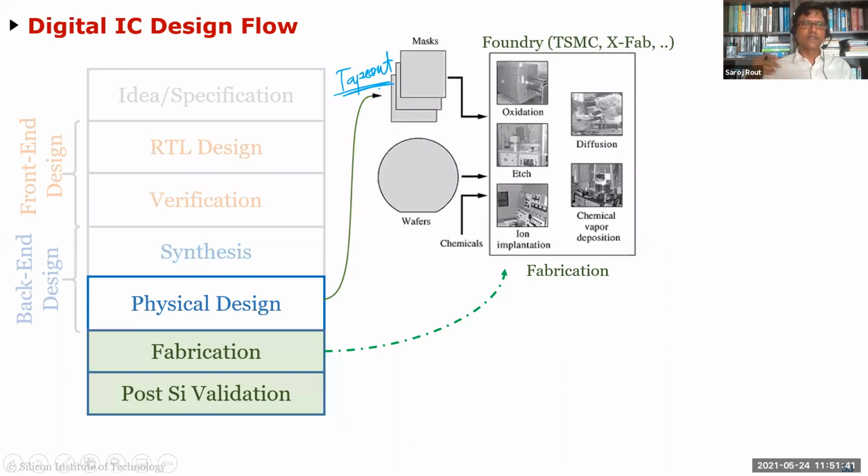And it's a legacy term. When IC design first started, it was physically sent to the foundries using tape drives, because that was the only memory then. Big tape drives, like you have probably never seen, the size of car wheels, with magnetic tape around them. Even a simple transistor design would be sent through tapes. So when they say tape out, it means that tape was sent out. And that terminology has still remained. So even when you go into the VLSI industry, they'll say tape out, tape out.